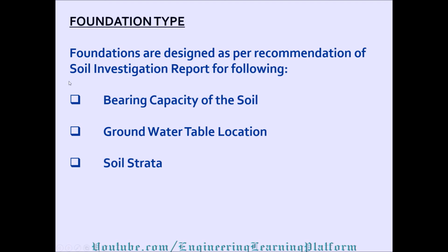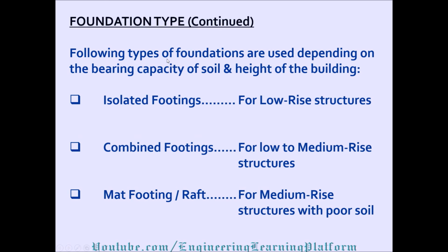Foundations are designed as per the recommendation of the soil investigation report, which covers the bearing capacity of soil, groundwater table location, and soil strata. On this basis, we select what kind of structure we would have, whether it should have a deep foundation or shallow foundation.